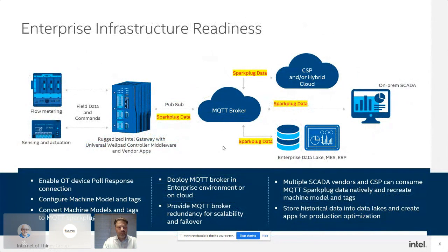So this is another view of sort of the same thing, from left to right: sensors, actuators. There's some field data, Modbus being one of the main protocols, but there's also OPC UA, proprietary protocols, and various different field buses. And there's a bunch of software things going on inside that device, for control, for optimization of the control, for collection of data, audit records, logging, alarms and alerts, filtering, etc. And so the idea is that we want to build that intelligence capability for the edge.